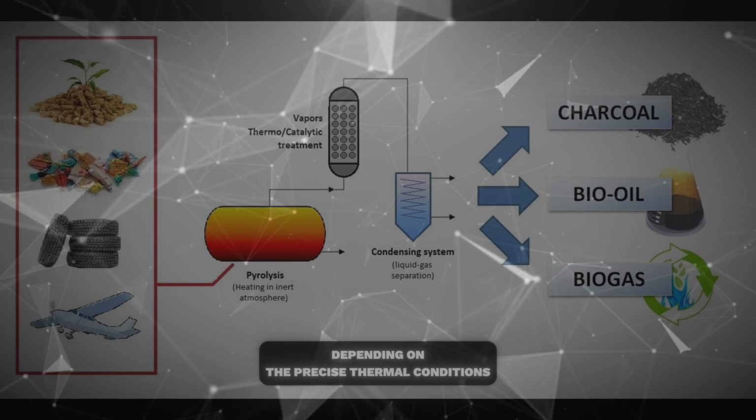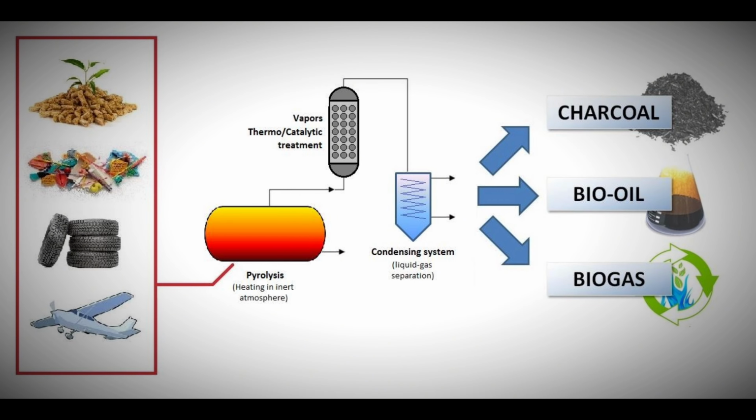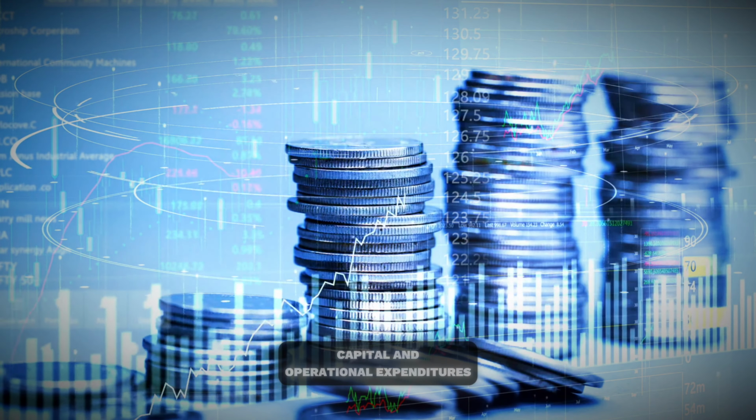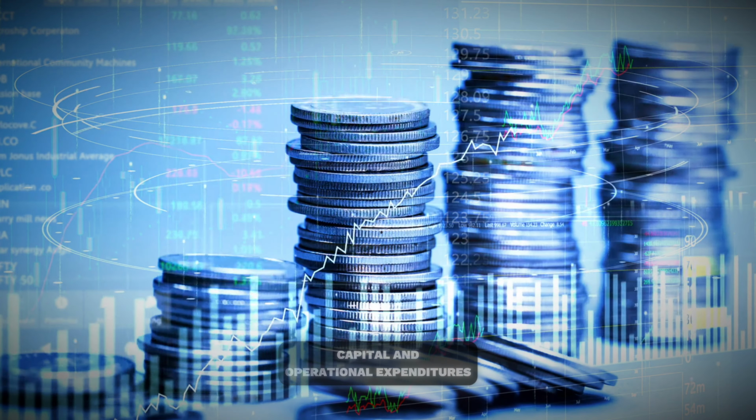Challenges and trade-offs in advanced waste-to-energy. While gasification and pyrolysis are attractive in models, they present notable practical challenges. Costs. They generally require high capital and operational expenditures, particularly associated with advanced reactor designs, synthetic gas conditioning, and complex gas cleaning processes. Feedstock handling.